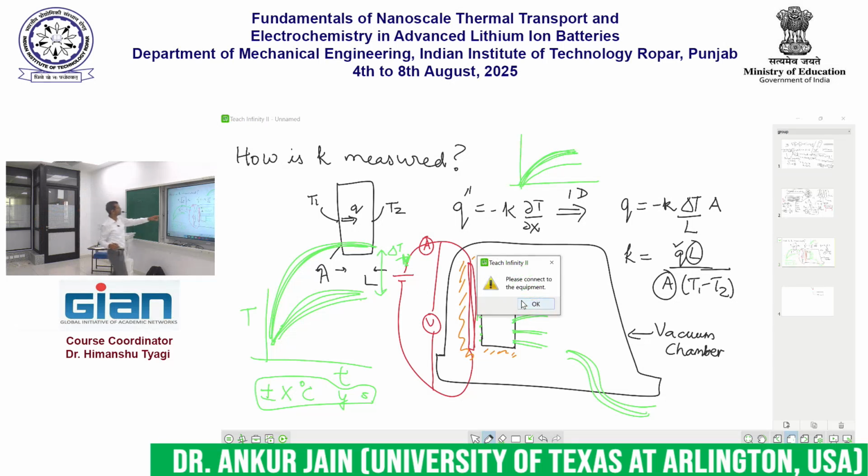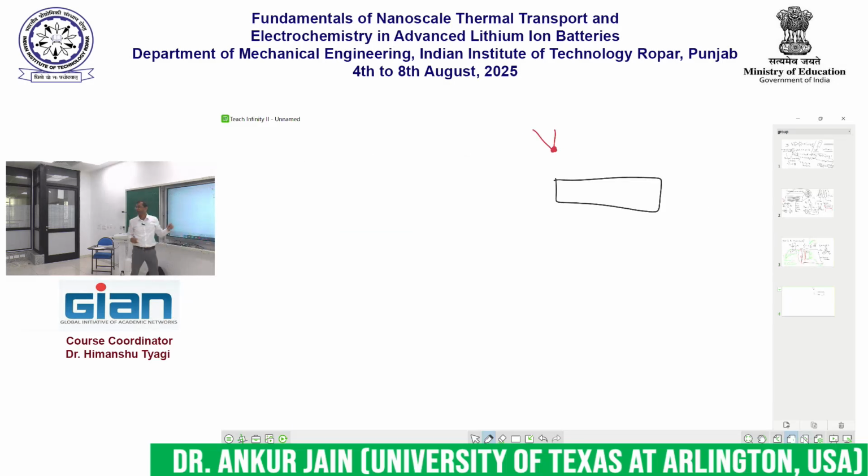Let's stick to thermocouples for a little bit. One more important question in a thermocouple is what is the size of the bead? This bead size is also something that Omega will ask you. Do you want a 1 millimeter bead or do you want a 200 micron bead? The price is significantly different.